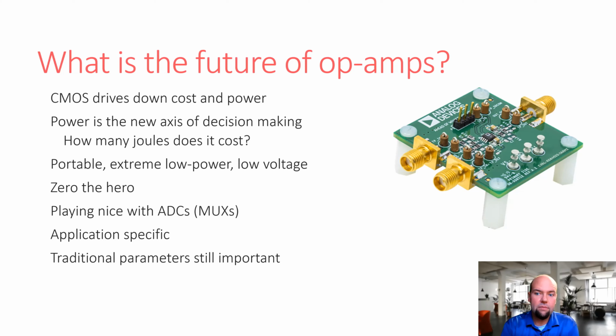Going back to the pulse oximeter example, a lot of them now are wireless digital devices that are battery powered, sometimes just by a coin cell battery. If you're trying to have something measure blood oxygen concentration, and it's a wireless device that runs off a coin cell, well, guess what? You're probably not going to want an op-amp that just burns 30 milliamps of current all the time, like some of the older op-amps did. If people need to switch out the coin cell batteries on my device every day, they're not going to want to buy it. They're going to go with a different company's product.